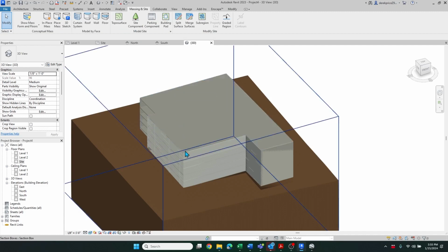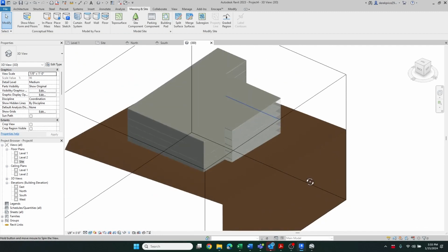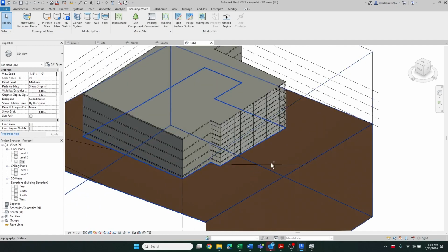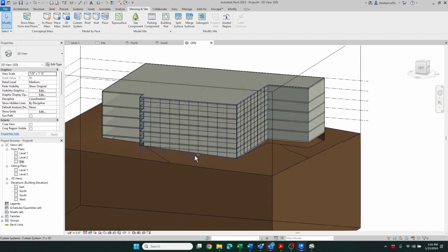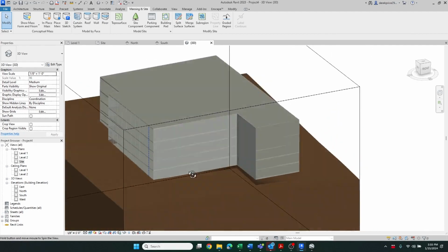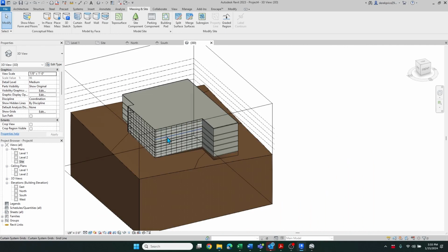Okay, now we've done massing to our first project. We've done a basic building, and you can see the curtain walls in there. What's nice about doing these massing models is that if you want to adjust the mass, let's say you're studying and you're like, okay, something needs to be moved in or out, or you've got too much floor area, then you can adjust the model. And there's a couple ways to do this.